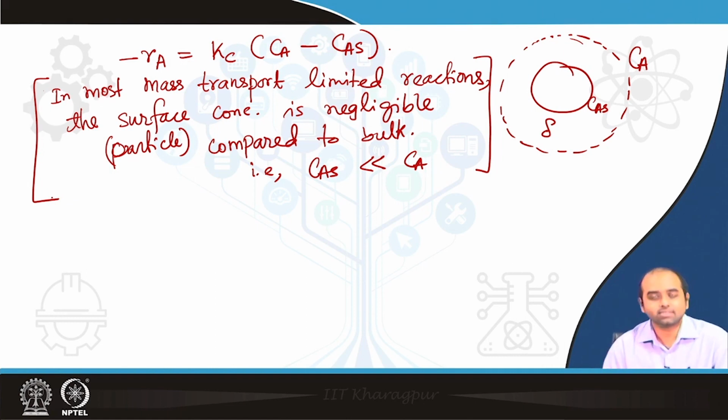But if it is a reaction limited process, or the reaction is the slowest step, it does not matter what the rate of mass transfer is. Then you can just write down the reaction kinetics for the problem, right. It is just like kinetics, and whatever reaction is happening in the catalyst particles will govern the entire system dynamics, because that is the slowest step.